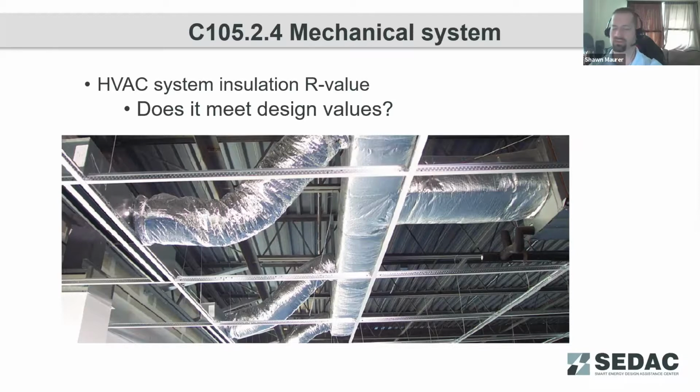For ductwork that's above conditioned ceilings, that conditioned ceiling space above a drop tile ceiling or T-bar framing for a ceiling is considered a conditioned area, so duct insulation is not required, although it is commonly installed for sound dampening, and we do recommend some amount of insulation for condensation control on that ductwork. Recognizing that with tighter building envelopes, we should not have outdoor air leakage into the above ceiling plenums in these spaces. But usually some instance of outdoor air leakage gets into these above ceilings, especially as they are used commonly as open return plenums for HVAC systems.